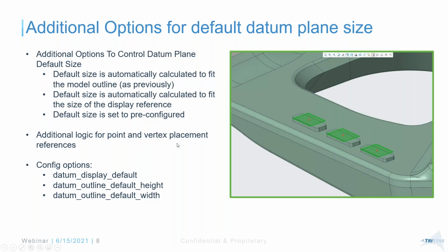Actually, one more option in the datum planes is one that I used during my industry days, where when I create a start part, I used to ensure that those 3 datum planes are quite small. I'll have to go redefine it, or create a small circle, because usually the first sketch you do will be like 500 by 500, some large value, because the size of the plane by default is set to like 500 by 500 or some value depending on the unit system you use.